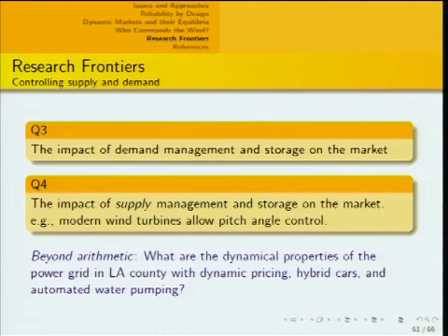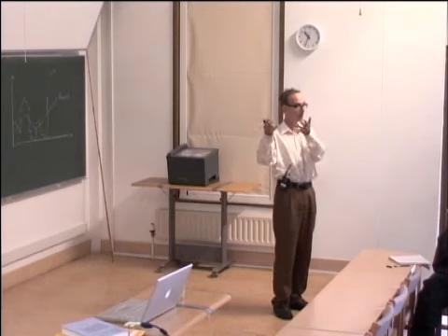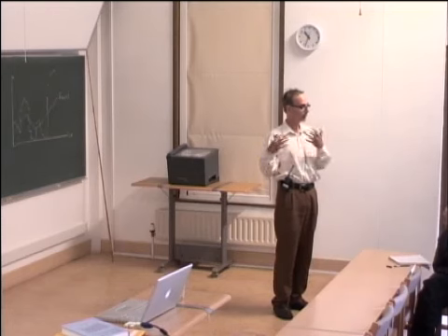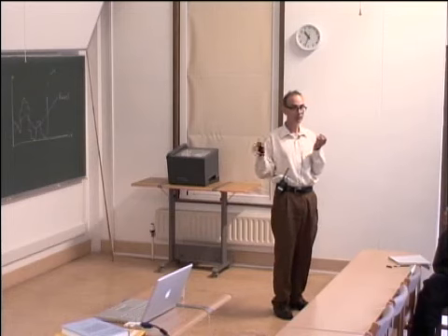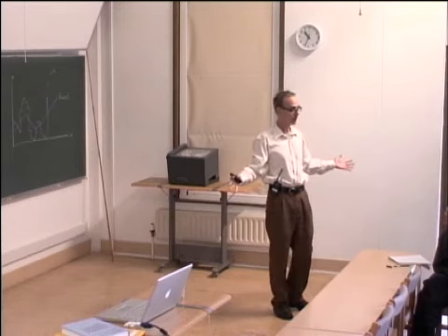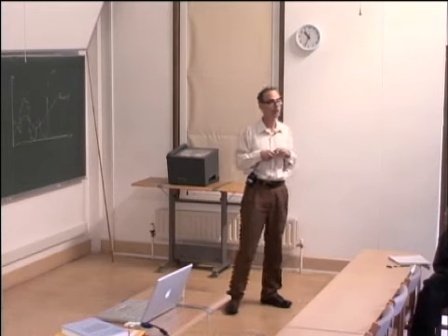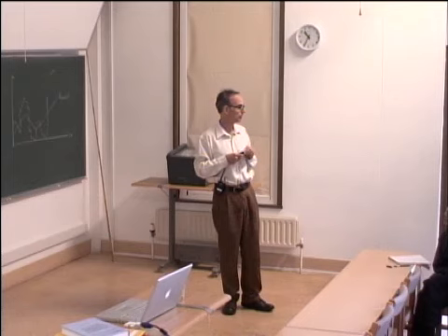It's not just adding up the bulk amount of power in this scenario or that, there are all sorts of volatility issues as well. As I pointed out with wind, even though wind is free, its volatility makes its value much less. And so when we talk about, for example, demand response, we now have a coupled system of generators ramping up and down and suppliers ramping down and up. There's delayed information possibly, dynamics, and we need to analyze that huge dynamical system and not just do the arithmetic of how much demand response is there.